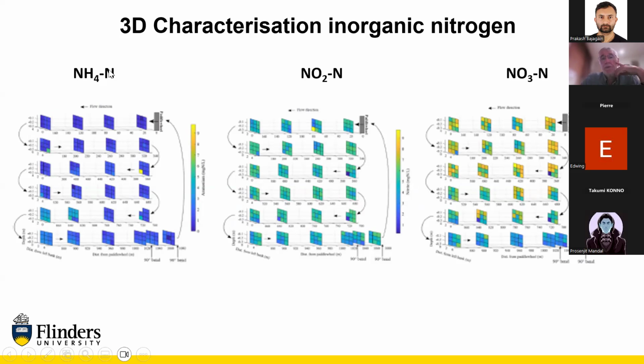But of course, what we talked about in the wastewater composition lectures and what happens to ammonia is where you've got high oxygen concentrations, which we have in the high rate pond, we will also have naturally occurring nitrifying bacteria. And we consider two broad classes of bacteria: the ammonia oxidizing bacteria, which will oxidize the ammonia through to nitrite, and the nitrite oxidizing bacteria that oxidize the nitrite through to nitrate.